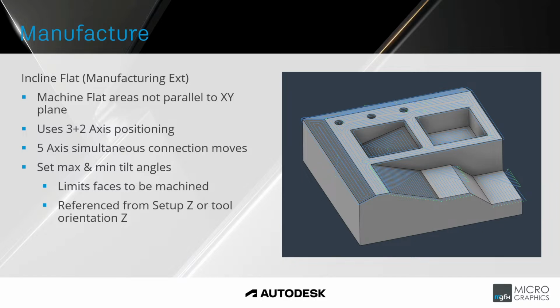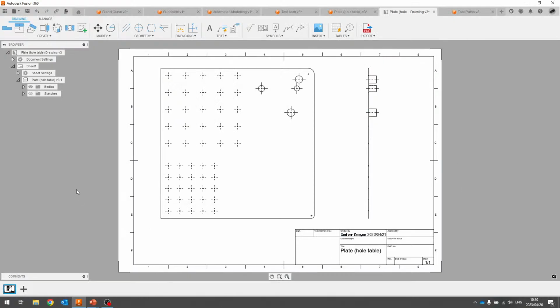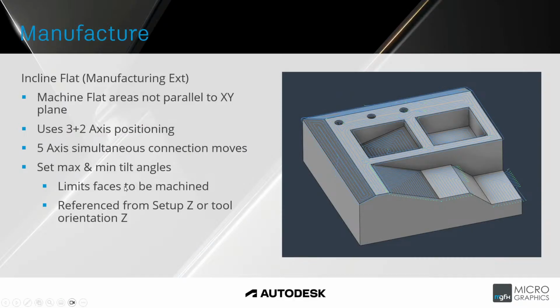You can see on the image on the right hand side, with the max and minimum tilt angles that are set on that example, the angled face to the right is not being machined because it is outside of those limits. So that is the inclined flats option. It's an included setting now within the flat toolpath.